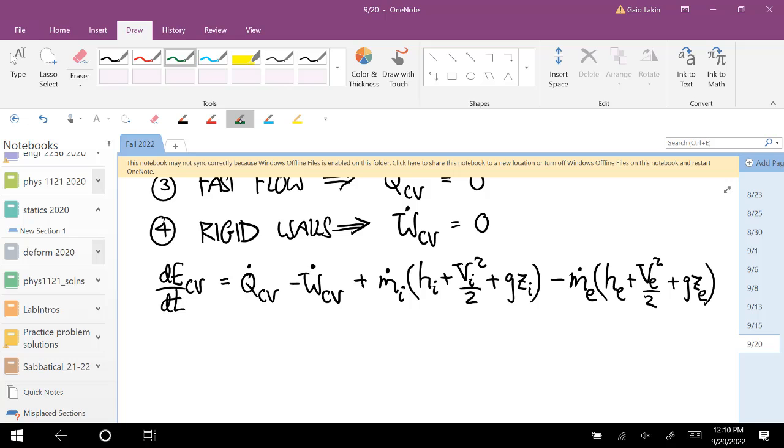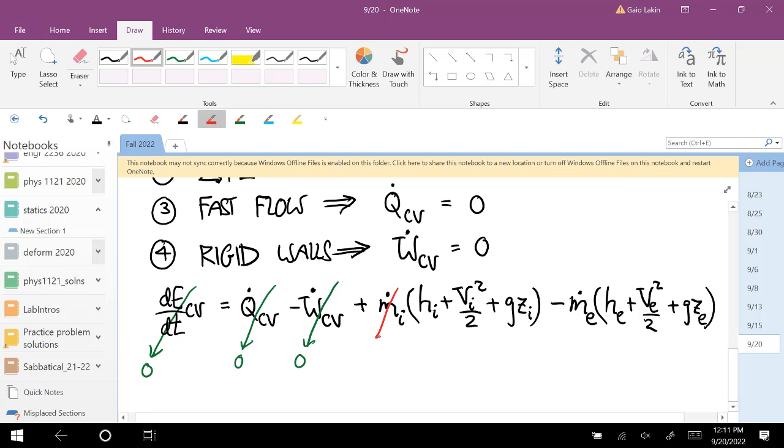All right, so this goes away. There's no energy term because it's steady state. No heat transfer, no work for the control volume. There's still that complicated work that we had to calculate, that came in and turned into the enthalpy term and stuff like that. But the walls of the control volume aren't moving, so there's no work done by the control volume. The mi dot, we're just going to call that m dot, same over here to me dot.